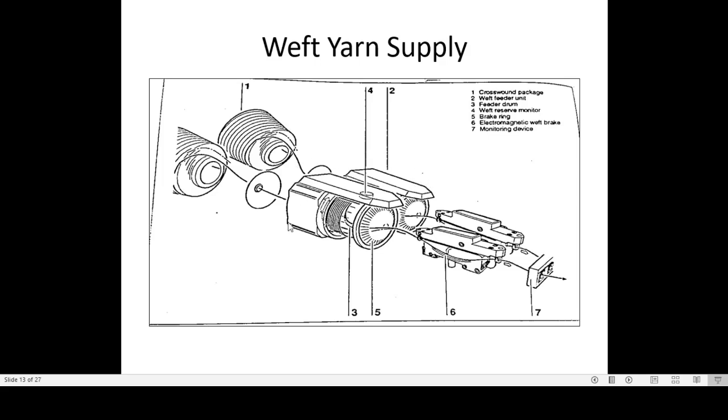The interesting thing is the accumulator here. The accumulator picks 2 to 3 picks of material, in the form of coil, and we are winding it on the drum. So this is the drum. The weft comes here, the fluff catcher cleans the weft. Here the weft comes in through this hole, and this is the winder. This arrow is the winder. It winds the coil on the drum.